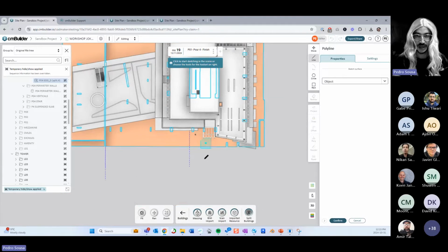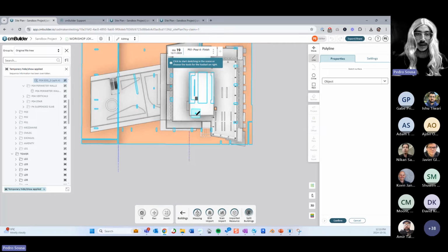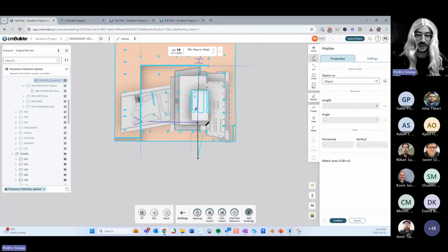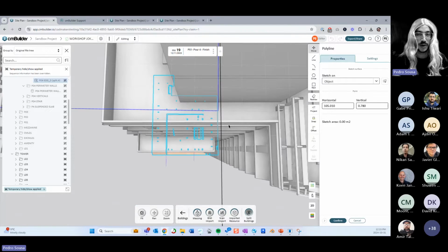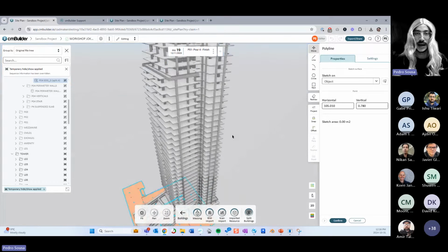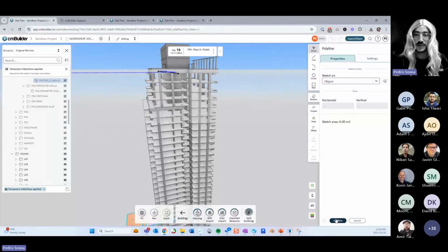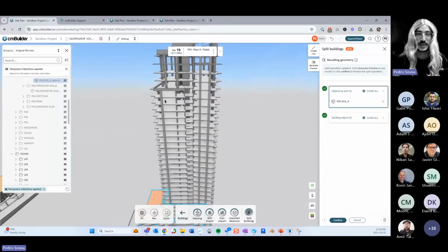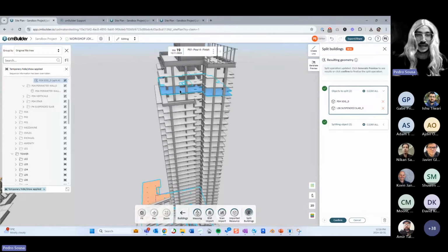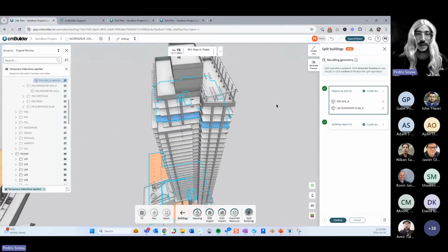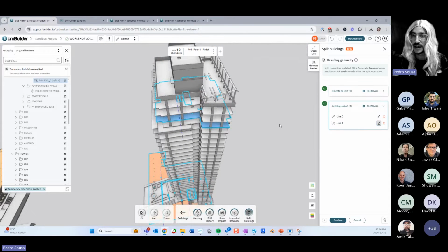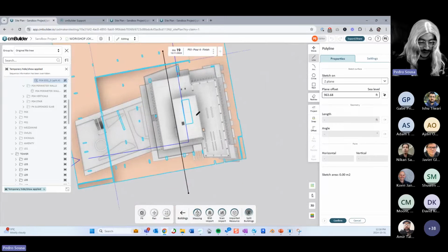But this sketch is going to represent just the split for the slabs on the towers. One thing that is super important about this tool is, let me just finish this part. So okay, split over there. I'm just creating my splitting geometry because I want to slice this slab using this line over here. Maybe I'm going to move this to the middle of that concrete.